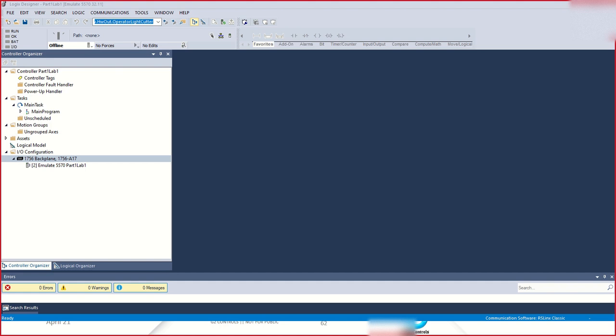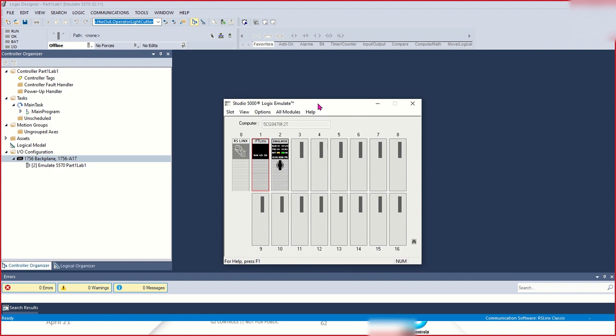That's why in the next labs, we are going to use soft code separately and hard code separately, and we can download the soft code and check it. For the hard code, we take a separate routine, and that separate routine we can inhibit, and then download it. But you can't download the same program on the physical controller and the simulation controller. It doesn't happen, because the physical controller configuration does not work directly with the emulator controller.